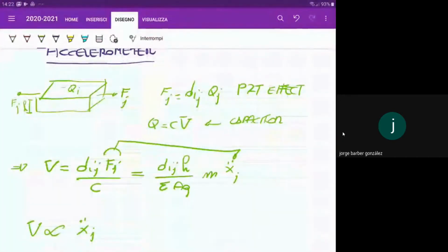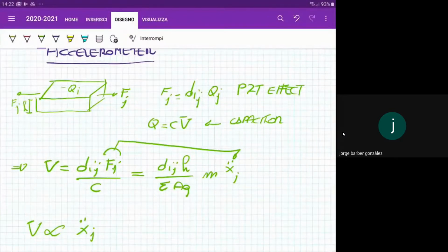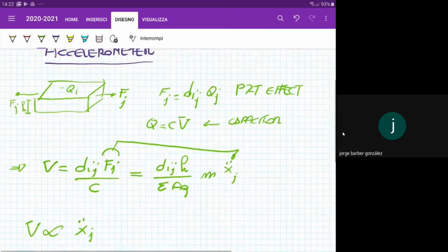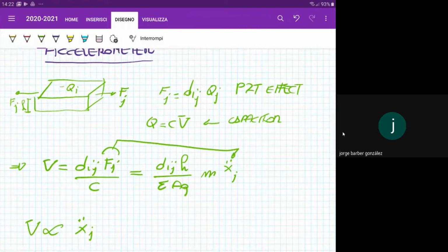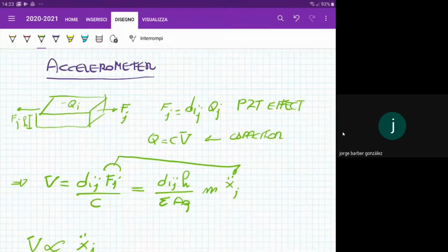By the way, the reverse effect, the actuation effect, is just having excitation from the electrical point of view through charges, and then we can have a reaction of this PZT just by exciting the surrounding structure with some force. However, for the PZT used as an accelerometer, we use this effect, and we also represent this PZT as a capacitor, electrical capacitor, from the electrical point of view.